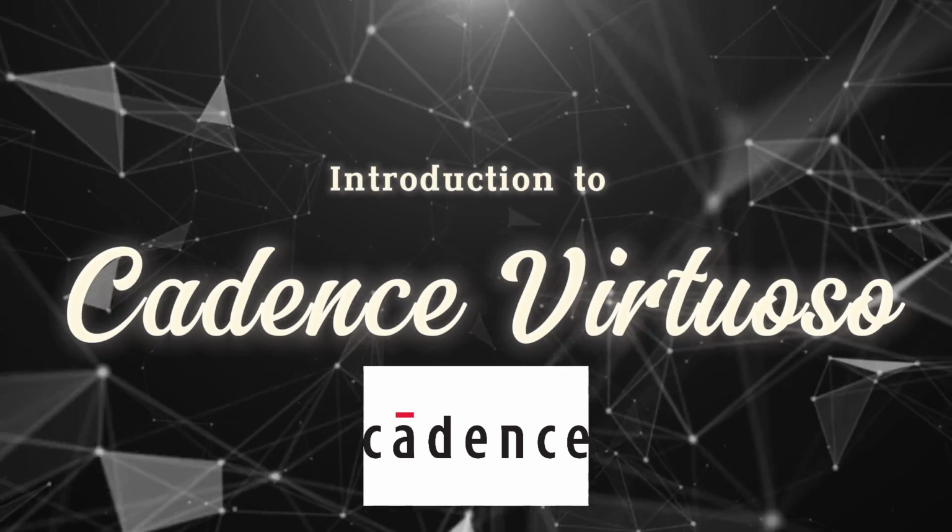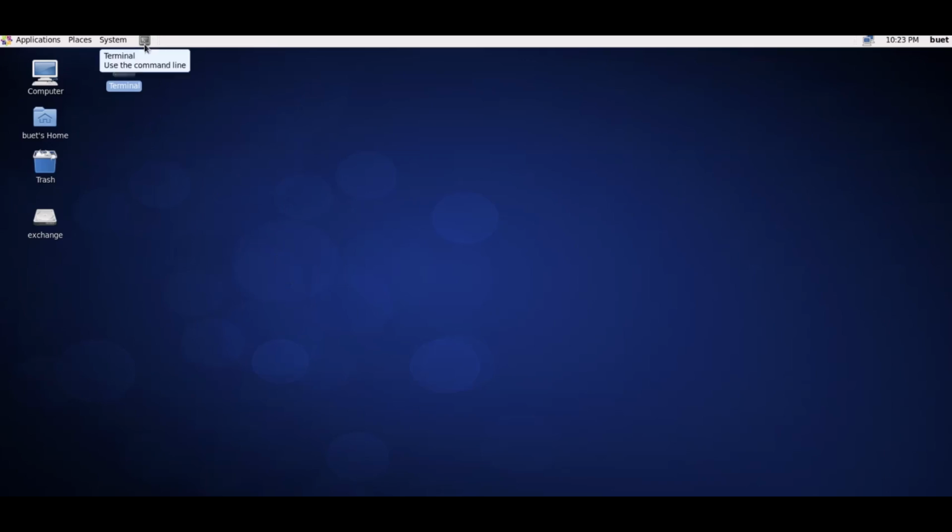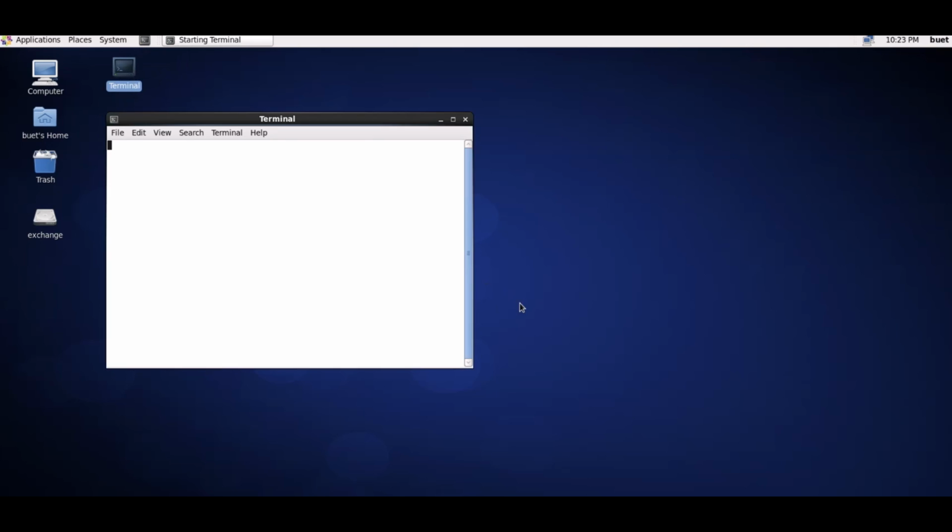Now, the first step is to open your Virtuoso environment. For that, just open your terminal window from desktop and type Virtuoso and ampersand, and the following window will pop up.